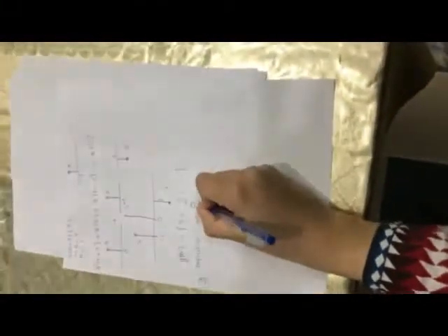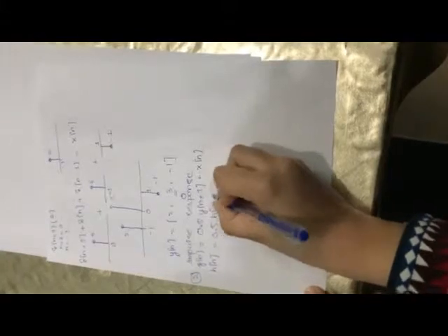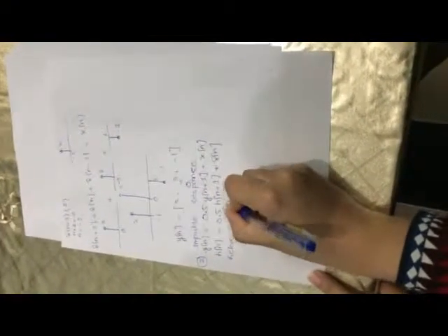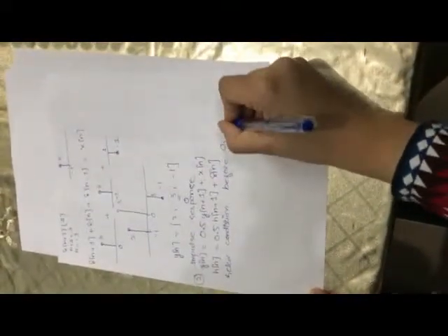And a second example of impulse response, in which the output response is involved at the input side. Let's say the system is something like this. We will replace y with h of n, 0.5 h of n minus 1, and x of n with delta of n. And we will assume here a relaxed condition. What is a relaxed condition? It means before 0 the system response is 0.